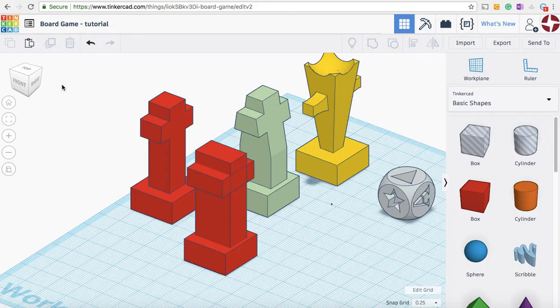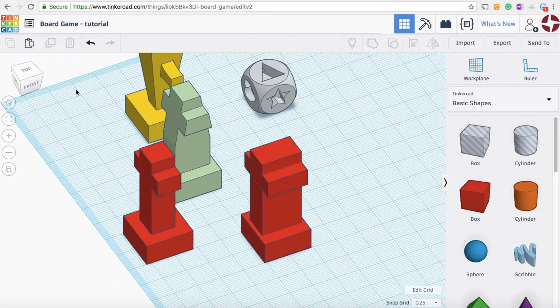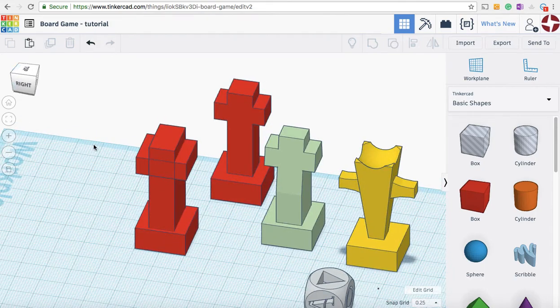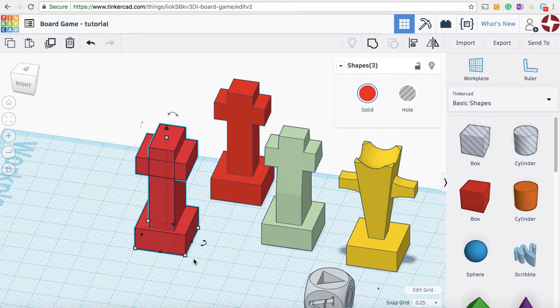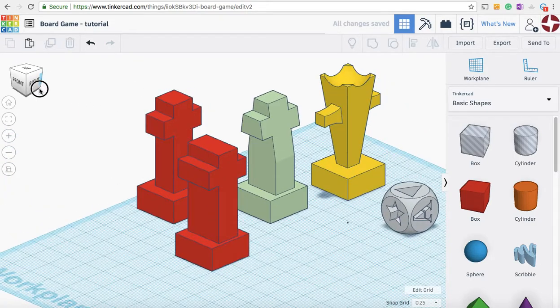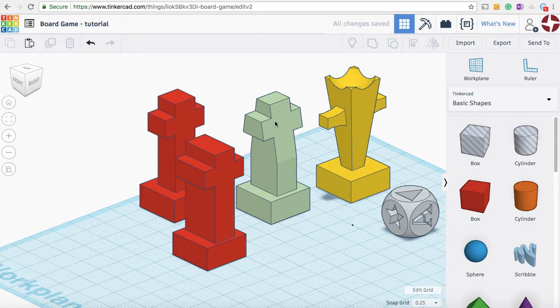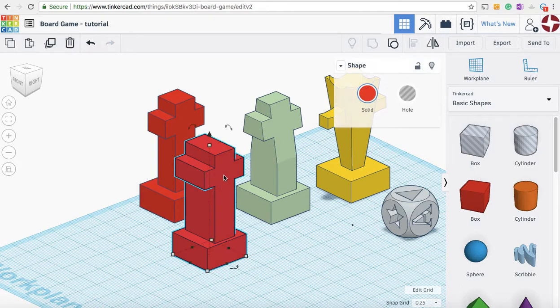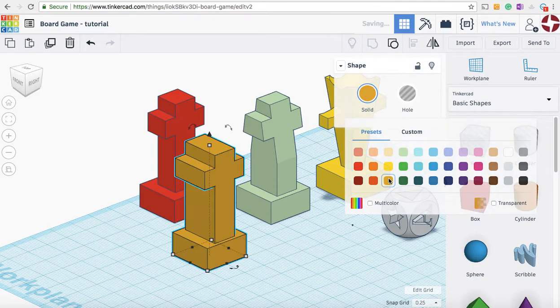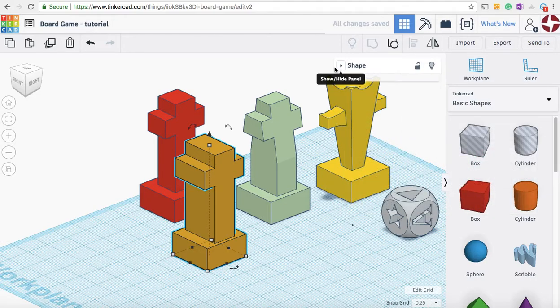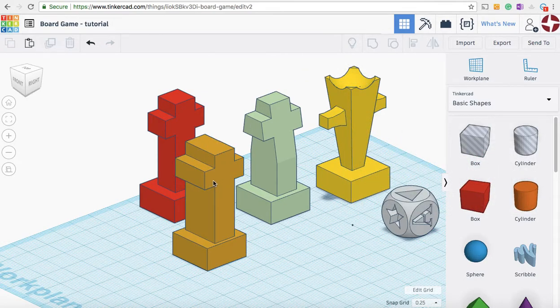Now, before I start doing these tapered edges like I've done there, I'm just going to regroup this design, because what I'm going to do, I'm going to start subtracting this material off the face. So I want this grouped, so when I start doing that subtracting, it subtracts from all the features, not just the ungrouped features.